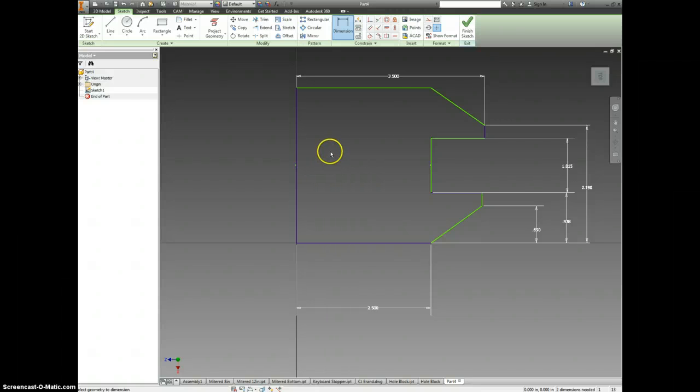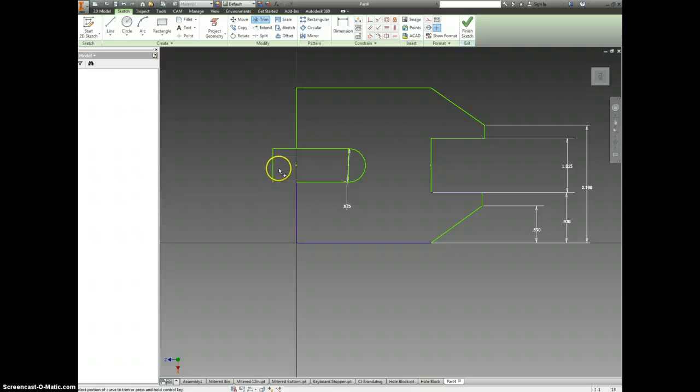Okay. If I were to extrude that, well, you know what? Let's just go and do this last part too. So there's a circle back here. It has a radius of 0.313 and a diameter is twice the radius. Let's multiply that by 2. Also going to draw a rectangle. I'm going to snap it to its 2 quadrants. Trim off the bits we don't need on this.